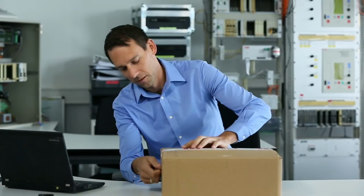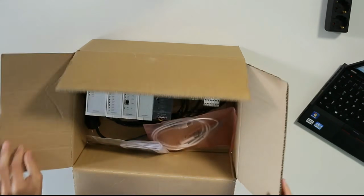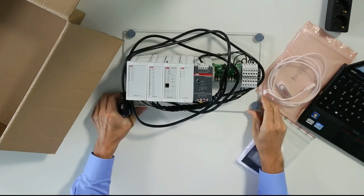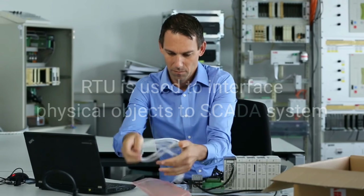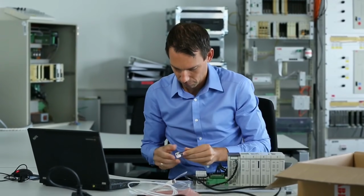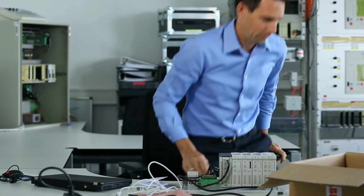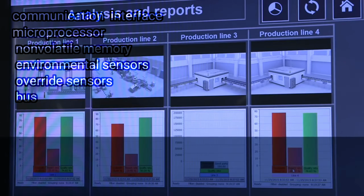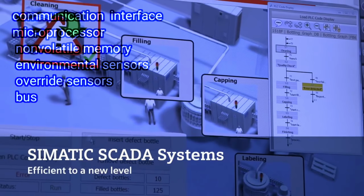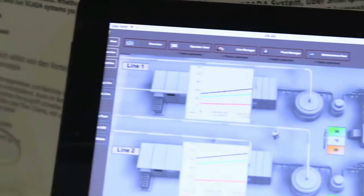An RTU is a microprocessor-controlled electronic device that is used to interface objects in the physical world to a SCADA system by transmitting telemetry data to a master system and by using messages from the master supervisory system to control connected objects. An RTU comprises a communication interface, microprocessor, non-volatile memory, environmental sensors, override sensor, and bus for interfacing.